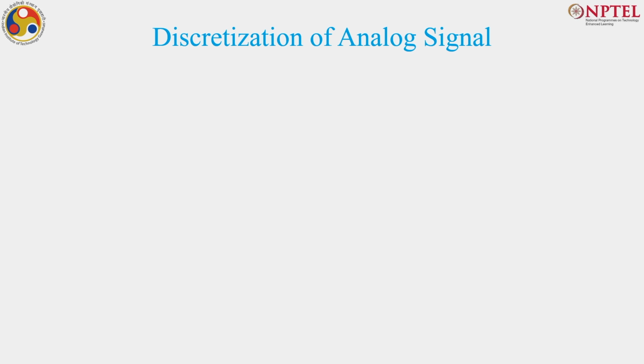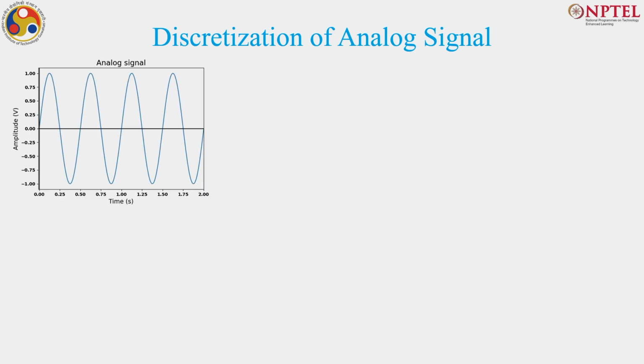So, how do we discretize an analog signal? I already said that the first step is sampling, but let us take an illustration. See, this is a sine wave. Now, this is not strictly a sine wave, this is just a part of a sine wave. You cannot ideally draw a sine wave on a hardware or any board, because a sine wave varies from negative infinity to positive infinity, and this is just a part of a sine wave where we have 4 periods. I say this sine wave has a frequency of 2 hertz, which gives the formula x(t) is sine of 4 pi t.